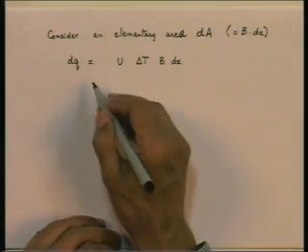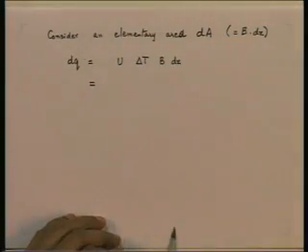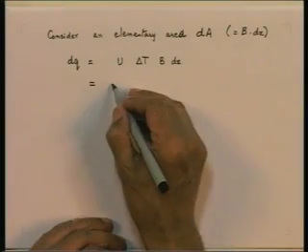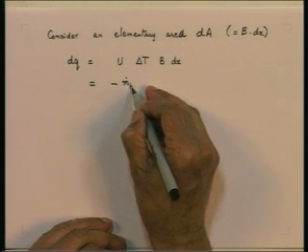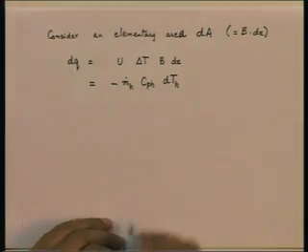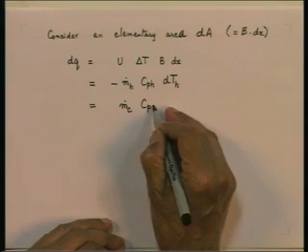Now, because this heat transfer takes place from the hot side to the cold side, the enthalpy of the hot side fluid decreases by this amount, and the enthalpy of the cold fluid increases by this amount. The enthalpy decrease of the hot fluid is seen by the decrease in temperature. So, over the length dx, the temperature of the hot fluid decreases by dTh. So, this must be equal to the change in enthalpy on the hot side, m dot h Cph dTh, and that must be equal to the increase in enthalpy on the cold side, which is m dot c Cpc dTc.